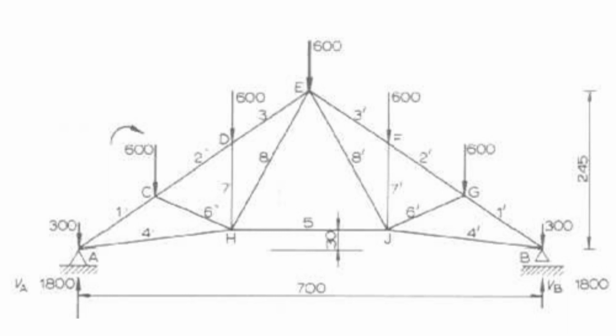Although in reality the joints are usually formed by bolted or welded connections, individual members of a truss are assumed to be joined by smooth pins. We can consider this a valid simplification provided the centerlines of the joining members are concurrent, meaning, remember, the centerlines intersect at the same point.